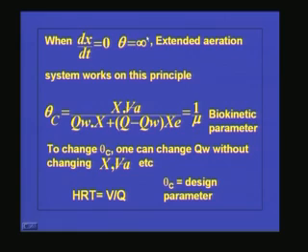The process modification of activated sludge, that is the extended aeration system, is working on this principle. Okay, there will not be any sludge wastage or sludge recycling theoretically. So there the theta C will be infinity, and all the sludge whatever is generated in the system will be undergoing auto oxidation, or they will be in that endogenous respiration phase. So they will be getting auto oxidized.